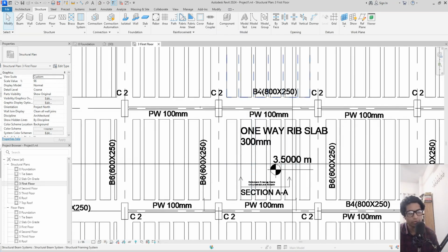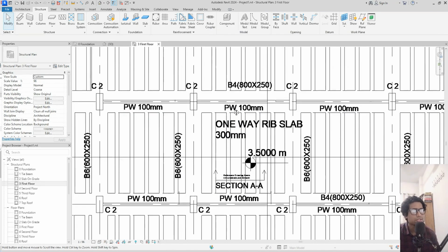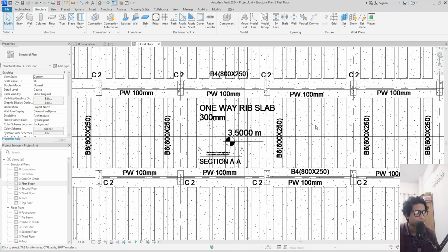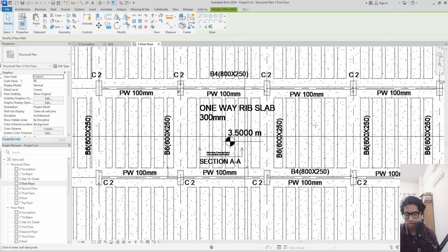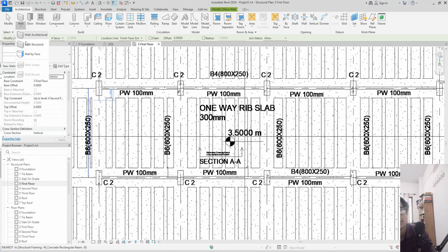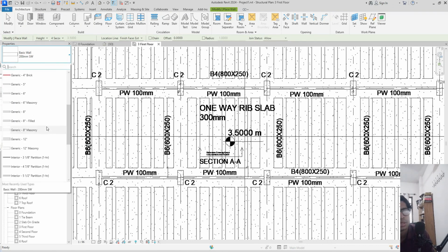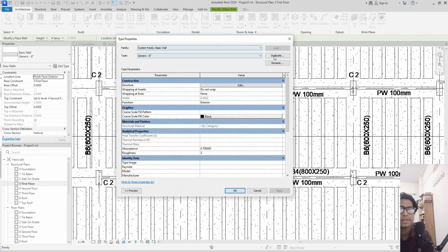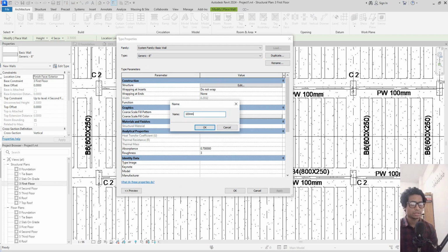Okay, WF wireframe, and you can see we have some partition walls right here, and this partition walls WA, there will be architectural walls, so wall architecture, generally 8-inch, and I'm supposed to make it a 100 millimeter partition wall.